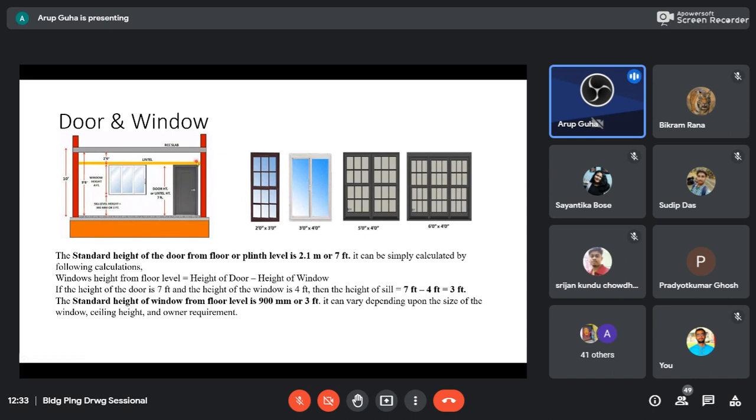ঠিক আছে? Then above that there will be a reinforced concrete beam which is called a lintel beam, and then once again the brick wall will go, and there will be the RC slab roof actually. Okay, তার বাইরে, if it is a one story building, there will be parapet walls, and this clearance should be nearly 10 feet. And in equivalence, actually 1 feet is 300 millimeters roundabout. So 3 meters.